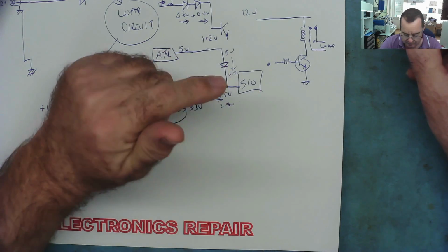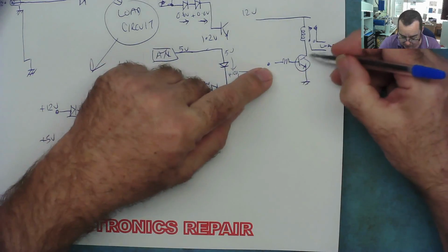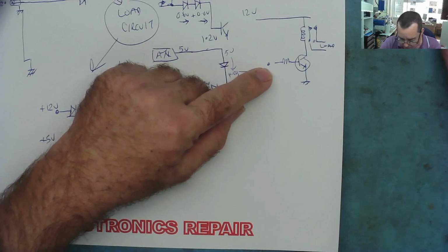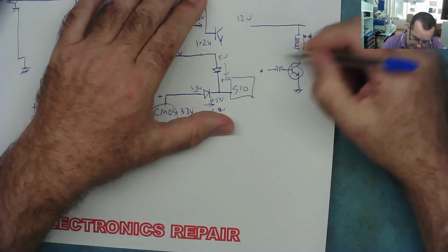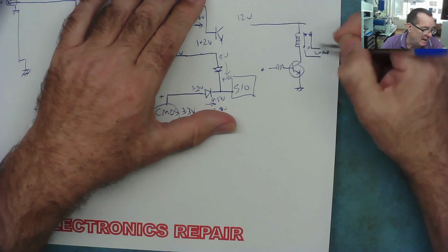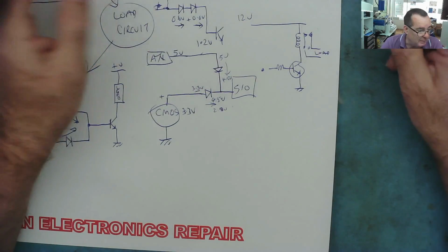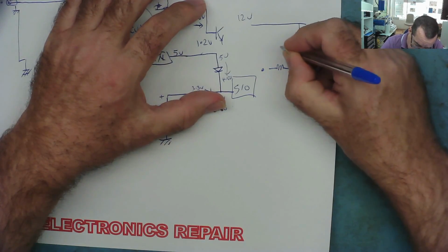This could be your little headlight switch on your car, which can't pass much current through the contacts of the switch. So it switches the transistor, and this switches your headlights relay, which then sends 20 amps or whatever into your headlamps. So effectively, it's just switching the headlamps without much current flowing through the switch itself. This type of circuit, you will always see a diode like this